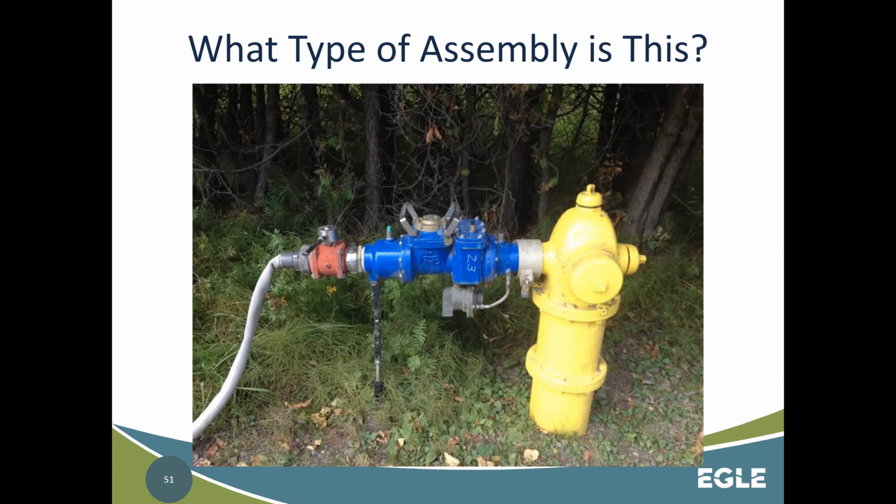I was looking for examples and quote, and I talked to a couple friends down that way. There was an entire subdivision of like 500 some people that were affected and got sick with an outbreak of fecal coliform or E. coli because there was a hydro seeding company in the neighborhood filling off the hydrant, and they had no permit, they had no RPZ, and had backfed into that entire subdivision stuff, chemicals and fecal stuff out of a hydro seeding truck.